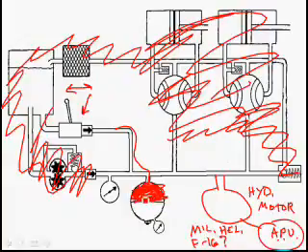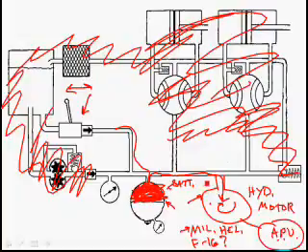So what you could do to start up the auxiliary power unit on these military helicopters is you would open a valve and let the fluid from the hydraulic accumulator go to the hydraulic motor, and the hydraulic motor would spin around, and that would spin the APU up and start the APU up. Literally, you would use the hydraulic motor and the hydraulic accumulator in place of a battery and an electric motor. Like in a Cessna 172, you'd have a battery to provide energy, and you'd use an electric starter to convert that electrical energy into rotating energy.